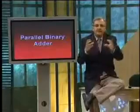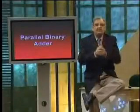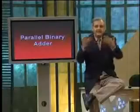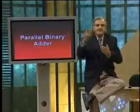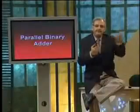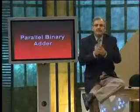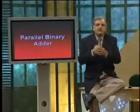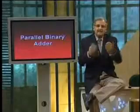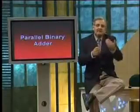We are just going to see the diagram representing a 4-bit full adder. Basically, the carry out of the least significant full adder. The least significant full adder would be adding the least significant 2 bits of the 4-bit number. So A0, B0 represent the two least significant bits of numbers A and B. So the least significant full adder would be adding bits A0 and B0. It would generate a sum output of S0 and a carry out of C1. Now, if this carry out is connected to the carry in of the next full adder, which adds bits A1 and B1, the output of the second full adder would be S1 and the carry out would be C2.